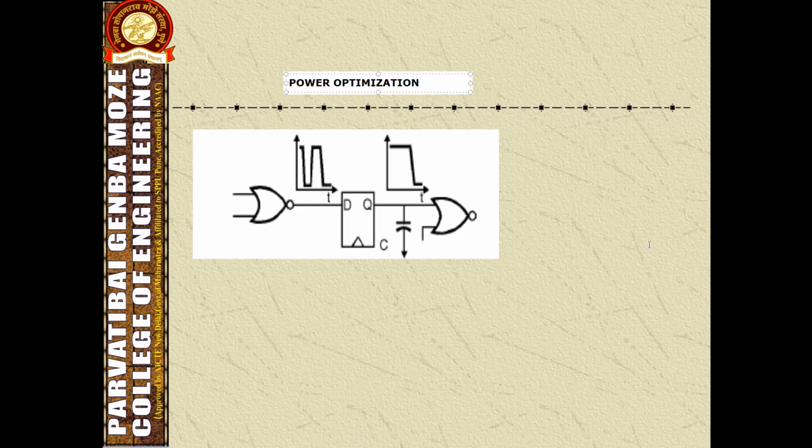In sequential timing optimization, what is considered is retiming, shown in the figure. The flip-flop is used to reduce the power consumption. A flip-flop is connected after the logic with the high signal transition propagation. For propagating and timing, an extra level of registers is added.